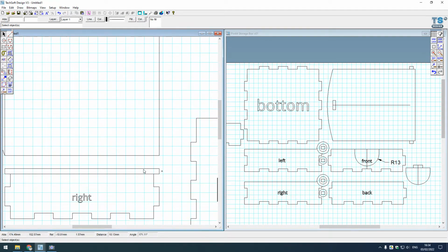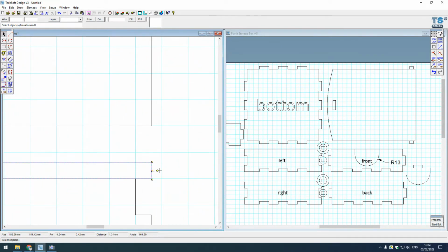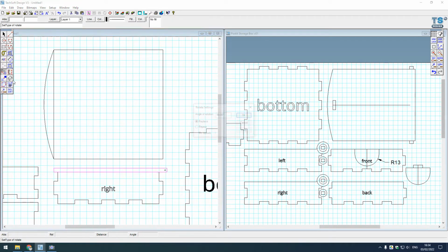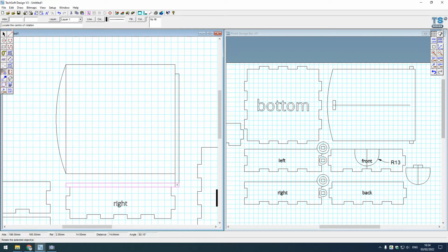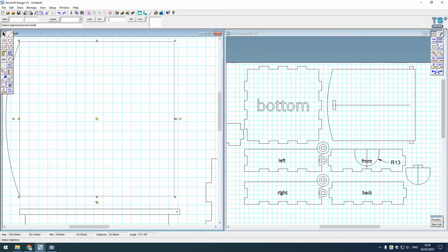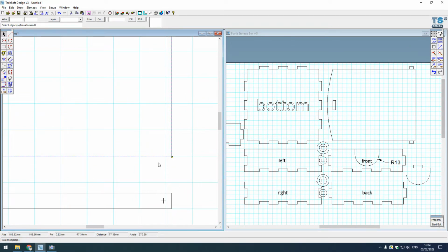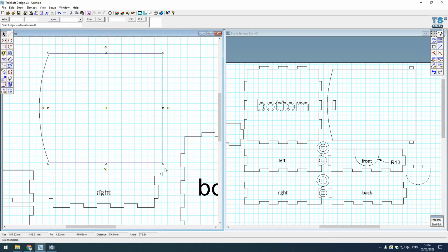What I need to do is take this design for the lid and extend it out 1.5, 3 millimeters, so that now if I do a transformation of this lid through -90 and repeat it once and rotate it around that hinge point, that's what we want. Okay, so bearing that in mind, I can now take this design right here, and I know that this needs to be extended out another 3 millimeters so that those two lines align. Okay, so that's now increasing the size of my lid as I want it to be.